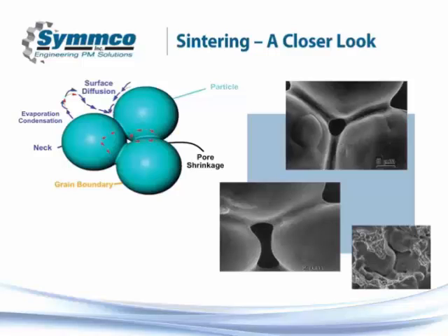In this case, as you see in that small caricature to the left-hand side, it is the energy that moves around every place those particles are connected to create a bond. One of the things that I use is, if you take your two hands and put your fingers together, the harder you press, the flatter your fingertips become. Those are essentially the bonds that we created in compaction. They are a somewhat elastic, slightly plastic deformation. We don't want to totally break all those particles.